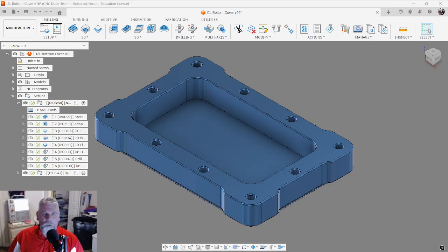When I worked in the industry, I was a setup man on the floor for a long time, and I had to set up and get jobs running for production. So that meant more than one part. I want to be able to load many parts without having to probe each one. And we like to get production like two operations at once. So we get two vices, we do op one and op two together, so we have complete parts if it's a two operation job coming off the machine.